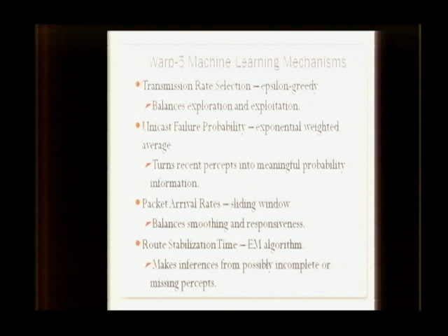In a slightly noisy environment, a slower rate is more resilient to noise, and will result in less transmission time. And it is that real transmission time that we're using to minimize. So in a slightly noisy environment, we want a slightly more resilient rate, a slightly slower rate. Whichever one does it in the least time is chosen most of the time, 95% of the time. The other 5% of the time, we try different, possibly faster rates to see if we can do a faster transmission rate and minimize the overall time, because the noise conditions might be changing for us.